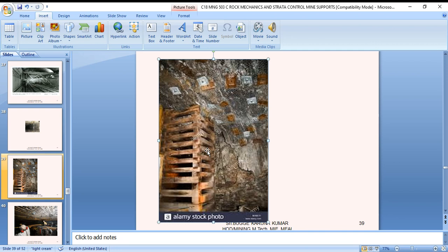Members of cogs are placed at a right angle over the members immediately below, in pairs. The cog chock is tightened against the roof by hammering wedges at a convenient height. When withdrawing a chock, the withdrawal of such a wedge loosens the chock and withdrawal of the sleepers becomes easy. The chock should be tight against the roof, and this may be tested by hammering to loosen the uppermost sleepers.